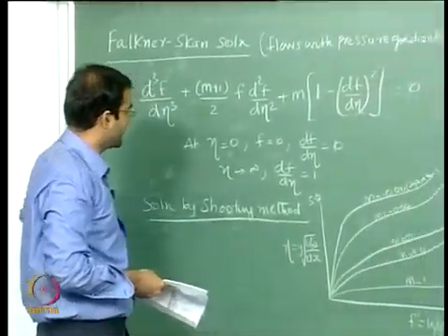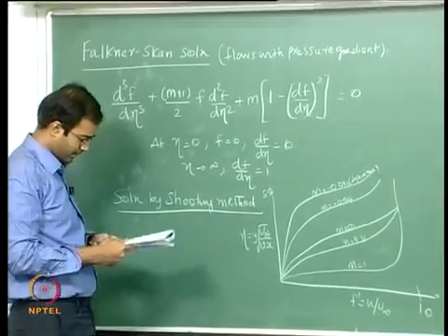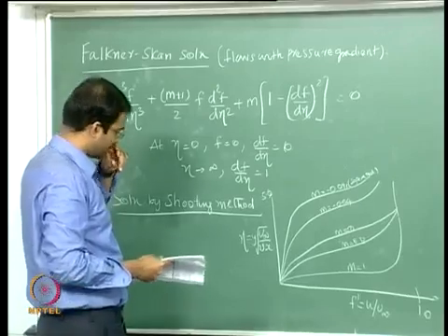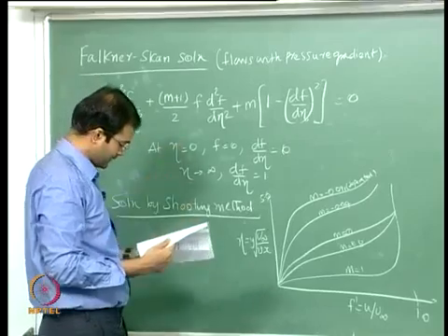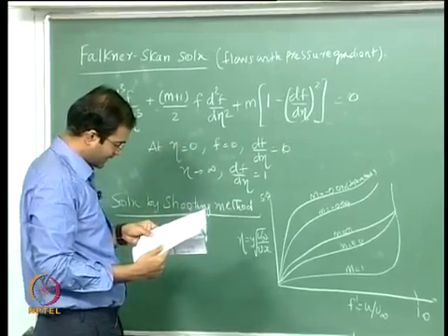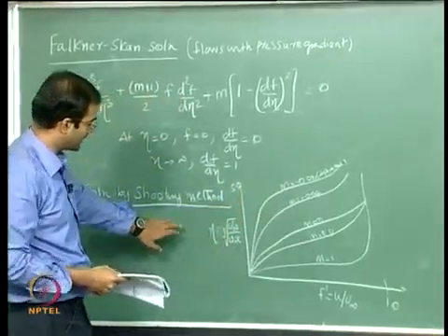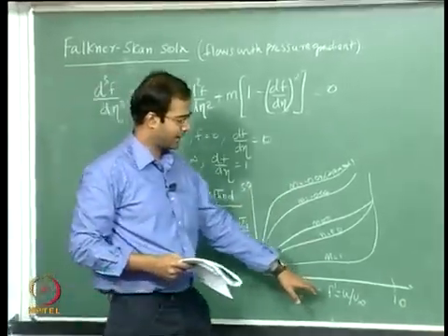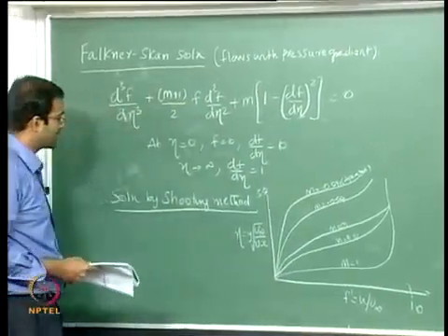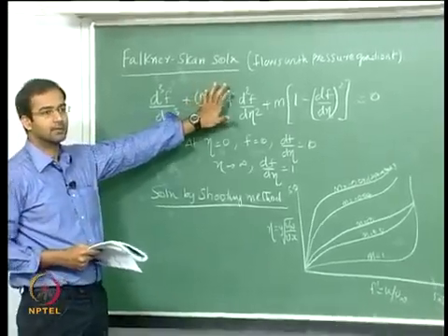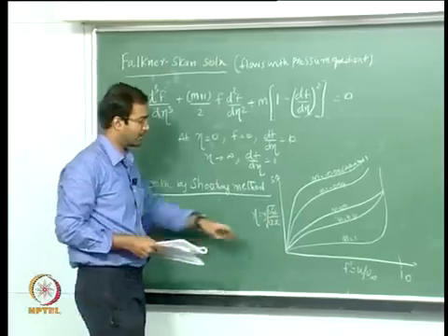So once you solve this, okay, so one more thing is that these are some of the velocity profiles if you solve the ODE by the shooting technique, and this is how the velocity profiles look, and these are the similarity profiles. So I am plotting eta on the y axis and f prime, which is nothing but the non-dimensional velocity, on the x axis, and I can substitute different values of m into this, and for each value of m I can solve the ODE by shooting method, and I can plot the profiles.